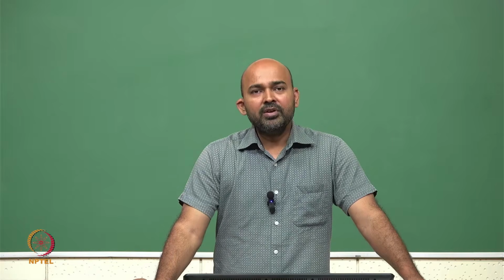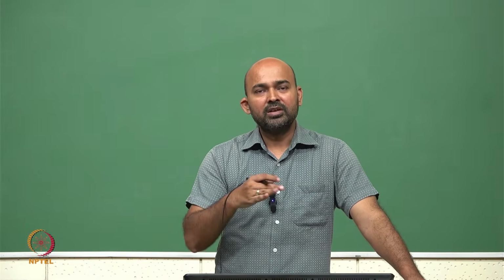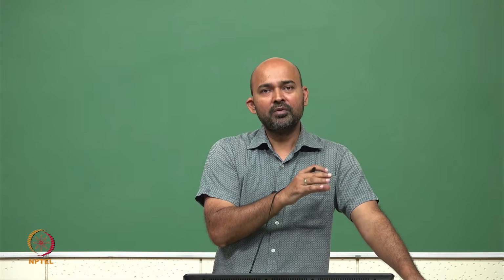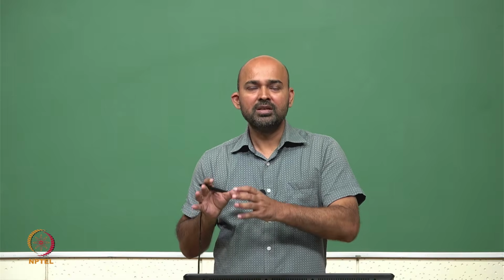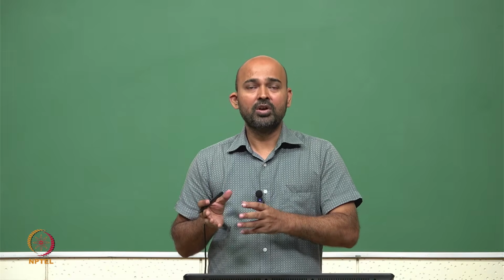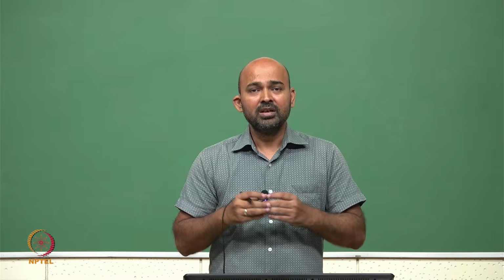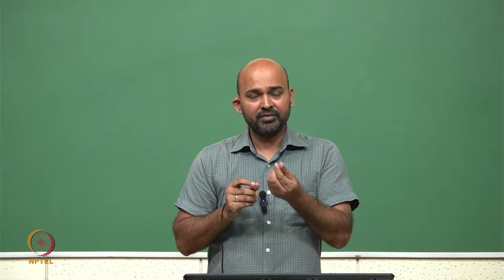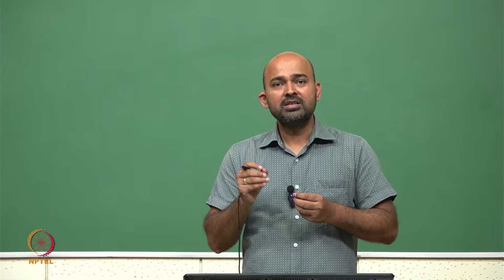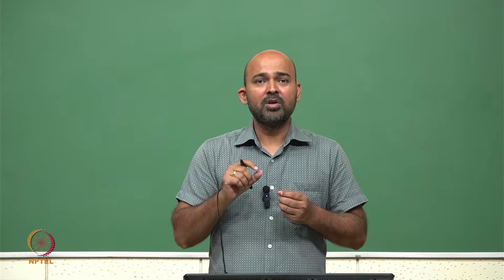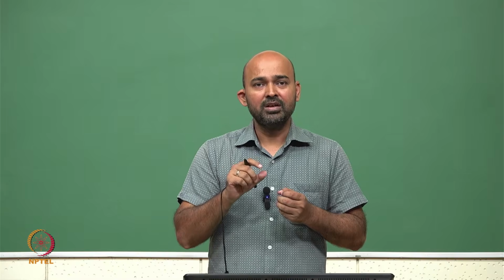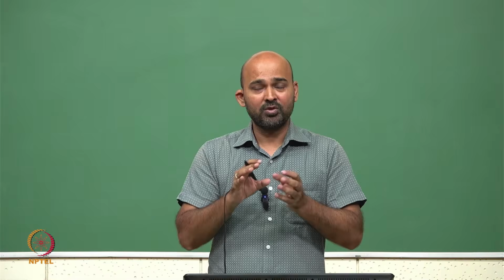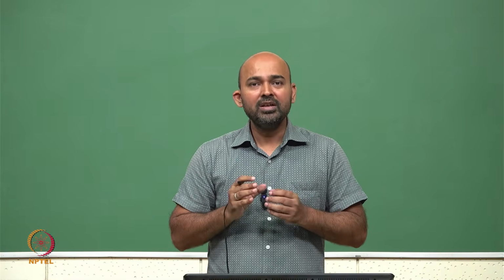So, delay we want as low as possible so that we can achieve higher and higher speed. However, to achieve a low value of delay, you have to increase the power dissipation, which is a bottleneck for modern day technologies, because in modern day technologies we have billions of transistors in a very small area. If each transistor burns, let's say, X amount of power, then we have 1 billion transistors burning this X amount of power, which is cumulatively very high.